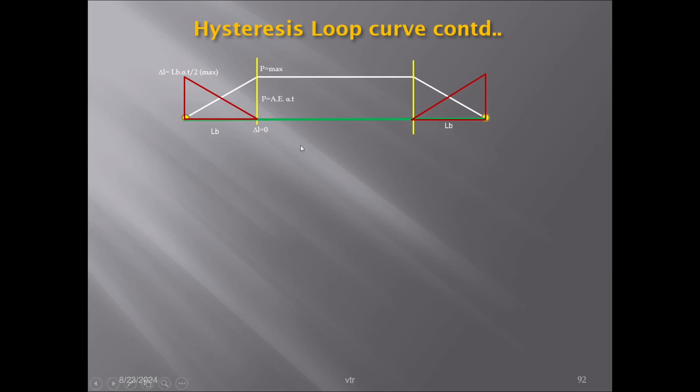I'll just put some lines. You can just understand first, then we'll go to the explanation. The hysteresis loop is due to the behavior of the longitudinal ballast resistance, because whenever there is an expansion, there is an offering of resistance. The ballast offers resistance, controlling the movement and stopping it at one point. That you understood.